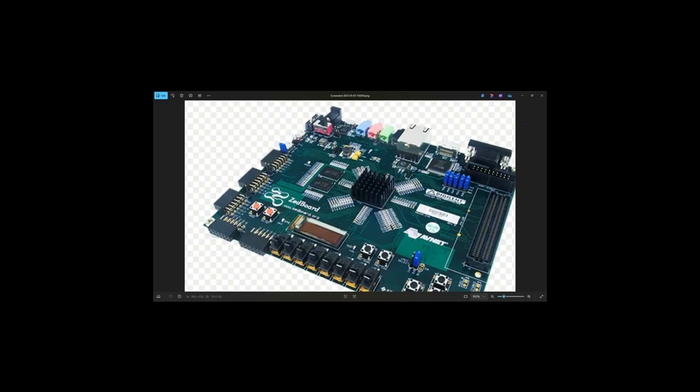The field programmable gate array is the core hardware platform used to implement and run the Snake game. Unlike a traditional microcontroller or microprocessor, the FPGA allows custom digital logic to be configured using Verilog. This has enabled us precise control over the game logic at the hardware level. All components of the game, be it snake movement, food generation, etc., are implemented directly as digital circuits on the FPGA as shown before.